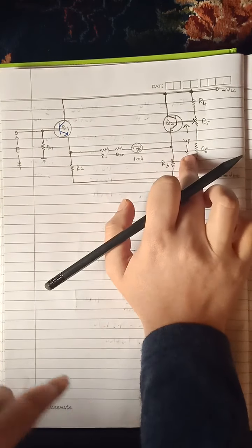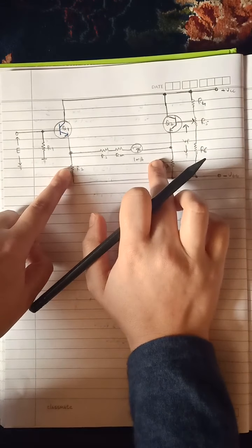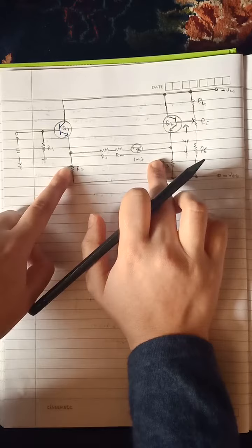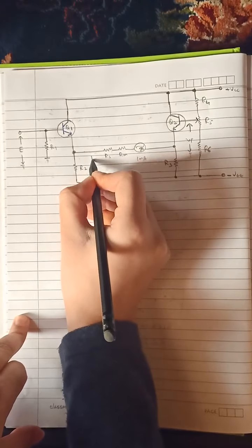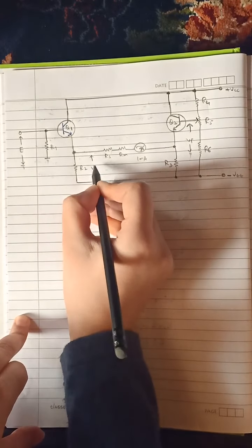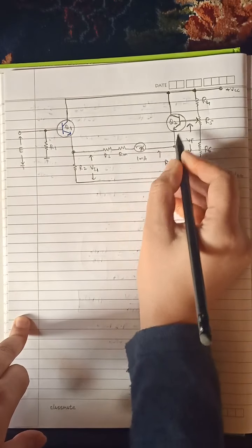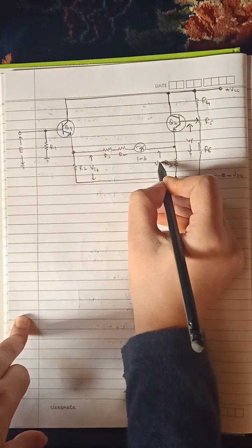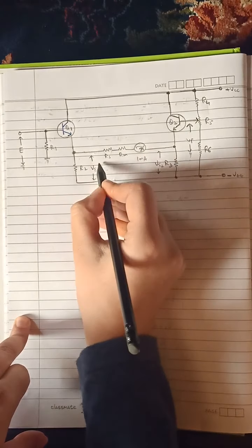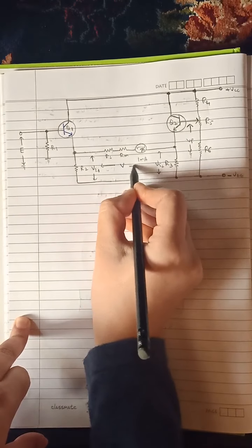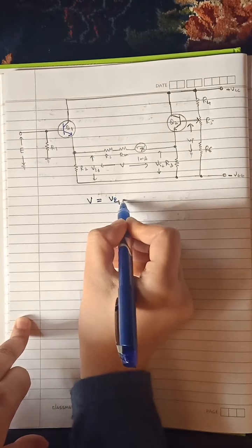So when this is equal to 0, we make this VP equal to 0, which will give you the voltage across this voltmeter 0. This voltage is difference from this point. Say I write this voltage to be equal to, since it is of emitter 1, so VE1, and this is of emitter second of the transistor Q2, so I will write this voltage to be equal to VE2. So this voltmeter measures the voltage, say V, and that V is equal to VE1 minus